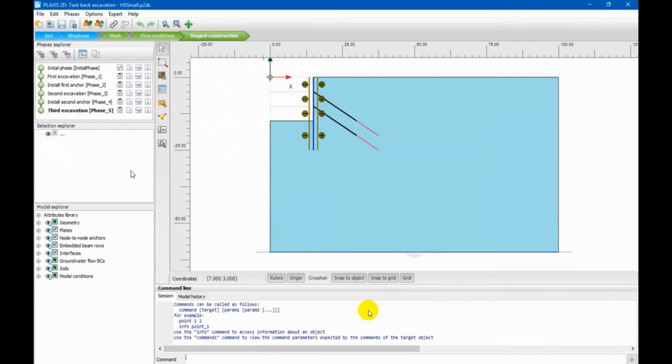So initially, when we see just an increase of stress level with depth, it automatically results in an increase of stiffness with depth. How you exactly put that in, we will see immediately after the presentation, after this homework presentation in the first presentation. And also the HS small model has the possibility to take into account that soil behaves even extra stiff, you could say, in case strain levels are being very small. So this was the homework assignment. We will go to the results in a short bit.